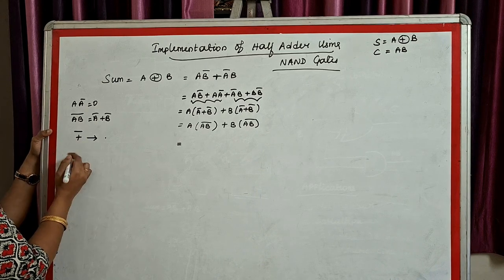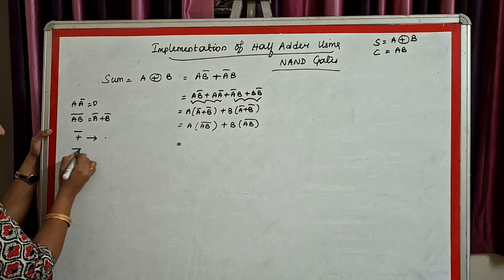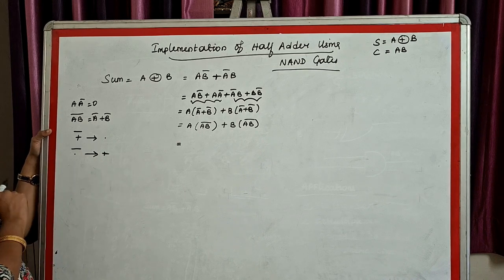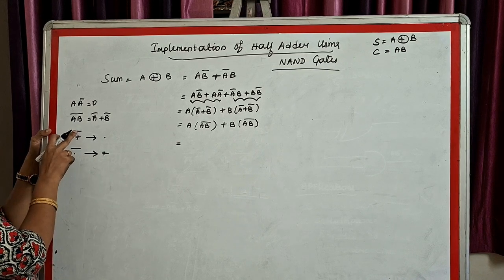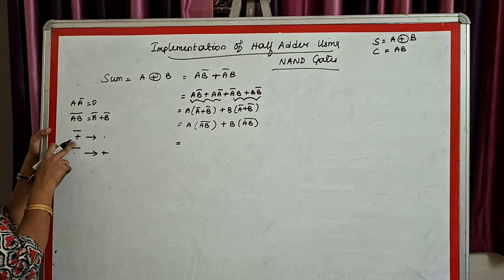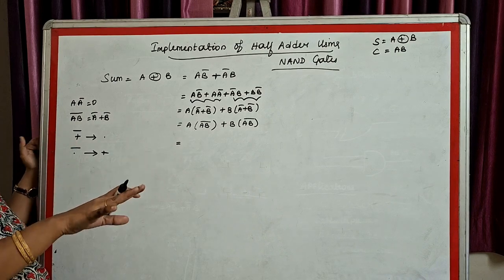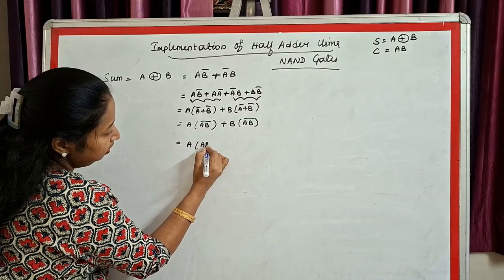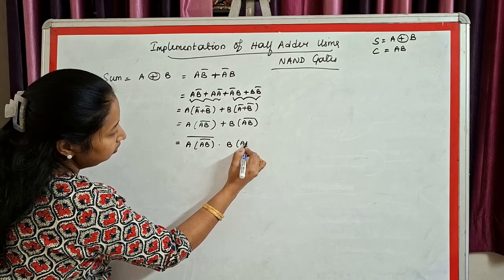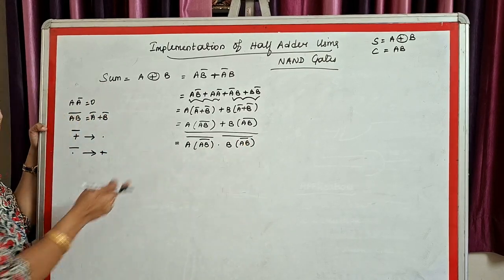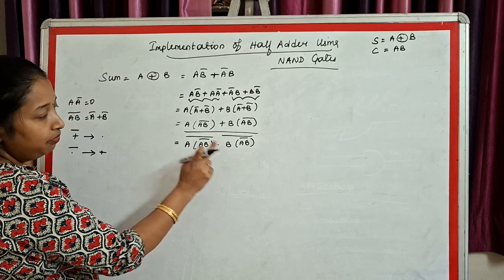Right? And the converse as well. In case you have a dot, the complement of a dot will give you a sum term. Clear? When you're taking a bar, you're not supposed to take bar only for the symbol. You have to take it for the entire expression. Clear? Now, expand it like this. Clear? This is how I'll be replacing this plus with dot product.